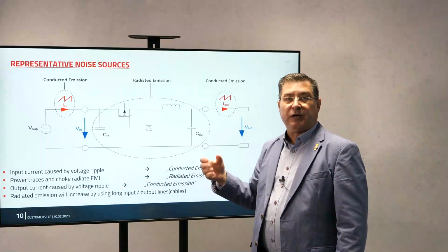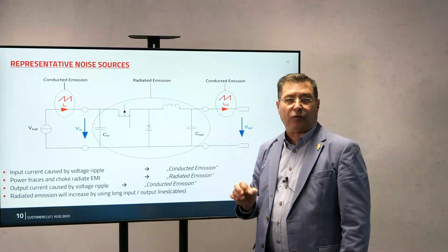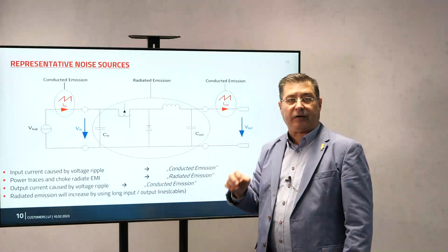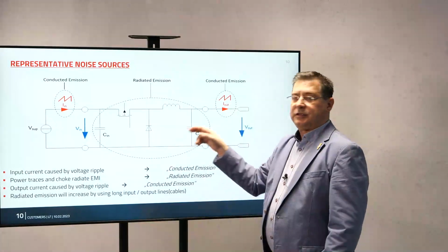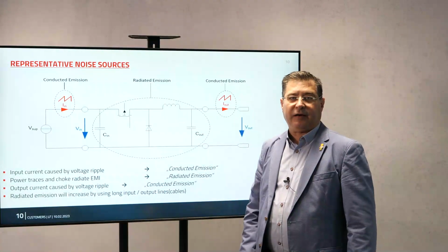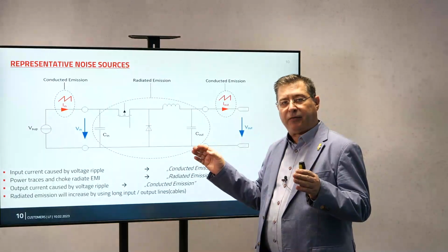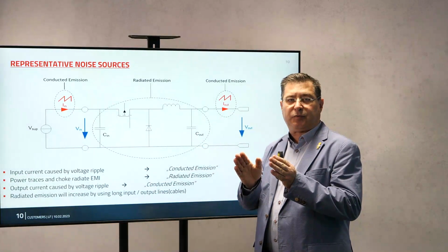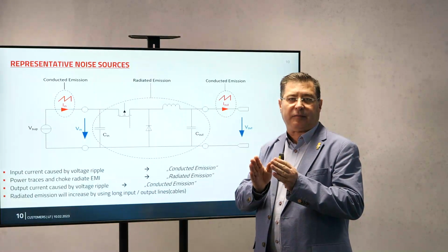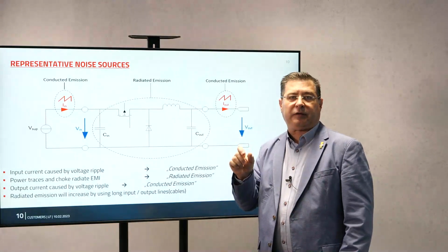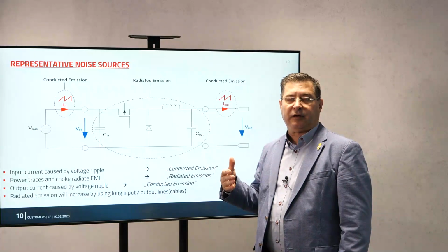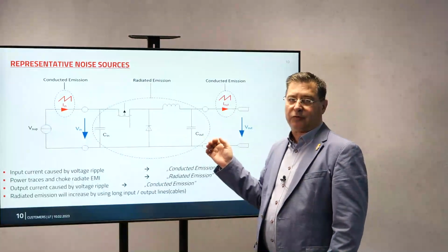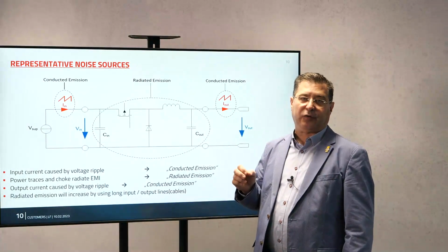this is the most emitting zone. So please don't push the auto routing button on your layouter, because when you make auto routing, you will not know where this is routed. And take care that this is made manually, and keep this track as short as possible and as little antenna as possible. 1 millimeter of PCB track is 1 nanohenry inductance. Consider that, and if you do not push the auto routing, you may have the luck that you have less